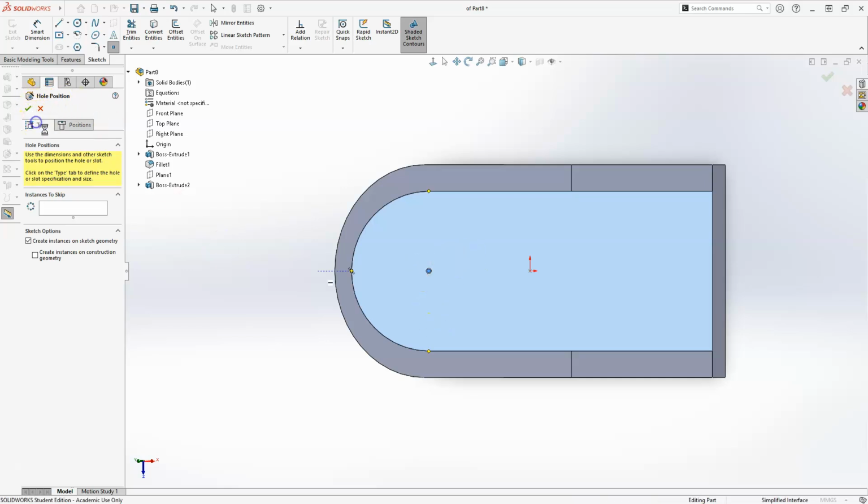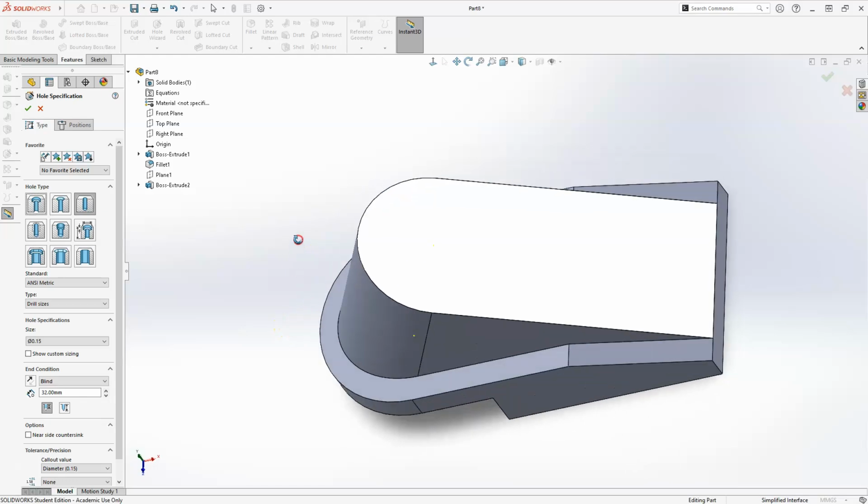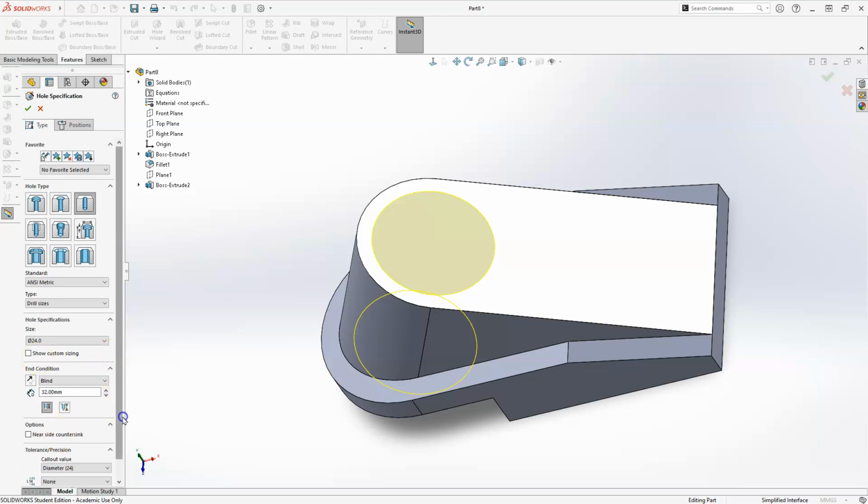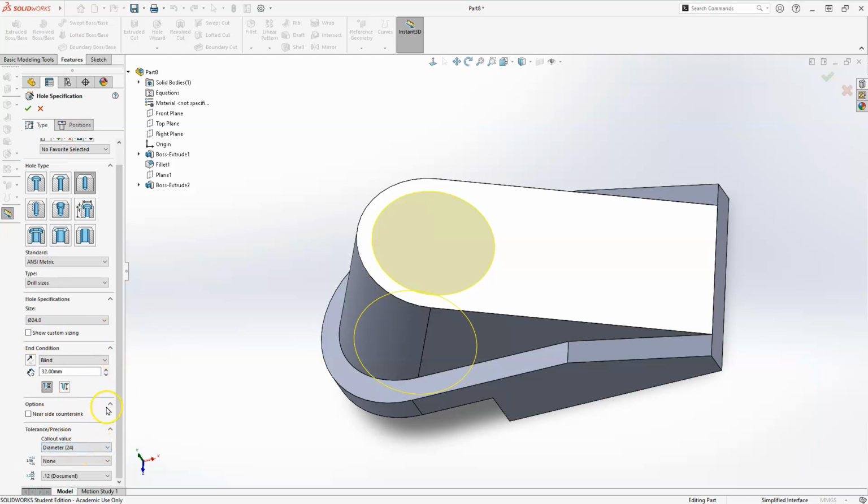Let's jump back over to the type and see if it actually gives me a large enough type. Oh yeah, the hole is super small on this one. This one has a diameter of 24. Now, I'm not using the custom size. This one I am using just a regular one that's pulling down from here. So I'm using this option. I got it set to drill size, and I uncheck my custom size. I am sending this one all the way through. So let's go ahead and change this to through all.